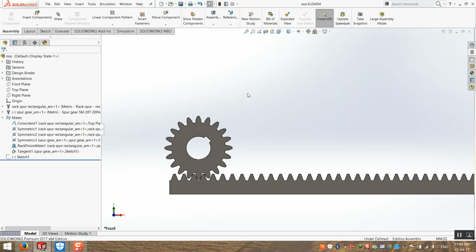It means this 2 centimeter axle or this 1 centimeter axle can rotate from point 0 back to point 0, a 360 degree rotation, 11 rotations per minute. You get it? You understood what's the difference? Any change in this diameter will change the full calculation. If this diameter is 1 centimeter and you put 2 centimeters, you are doubling the rotation. Instead of 11 rotations per minute, you become how much? 22 rotations per minute. Because why?